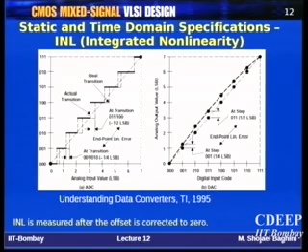Eventually that means that if you add the DNL from the first code, you reach the particular code that you desire, say 0, 1, 1, and you will get INL. INL is actually the summation of these DNL values when you reach here. And INL is always measured after the offset is corrected to 0. So first this plot, whatever it is, will be shifted to 0, the offset will be compensated, and now INL will be measured, because the effect of offset should not come into the picture.